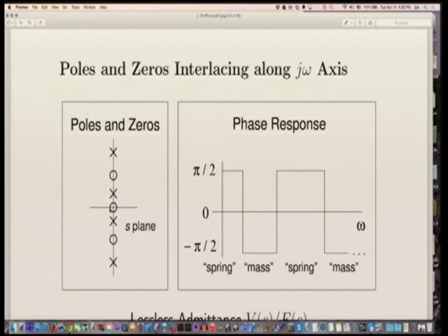It's a purely imaginary reactance, we say. Reactance, susceptance. It's a purely imaginary thing. It's got a phase of either plus or minus pi over 2, and there's never, at any frequency, any dissipation. Well, there's clearly a loss at the zeros, so you do get these point losses, but the bridge generally does not accept energy.